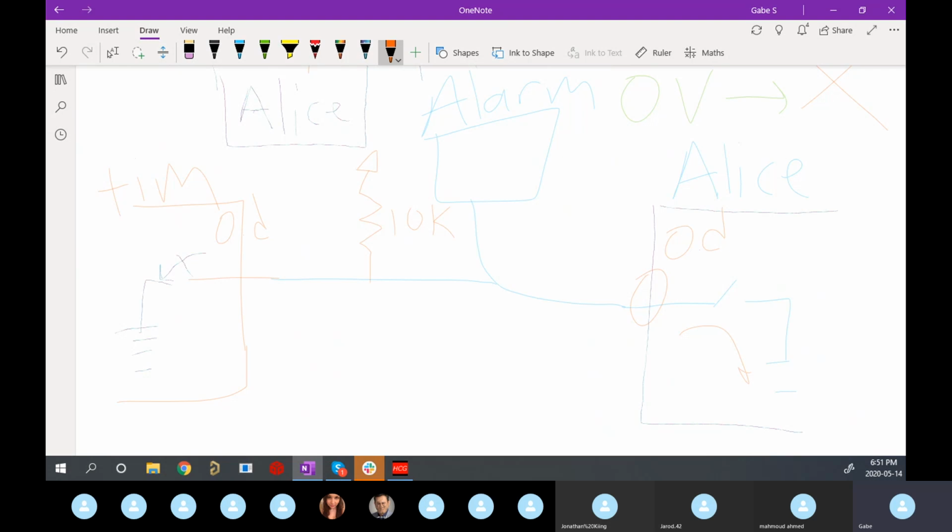We're not going to have the situation where Tim forces this to 3v3 and Alice is forcing it down to 0 volts. Neither of them have the capability to do this anymore. So if any of them see a fault, they can both, or just one if only one sees a fault, close their switches. For example, this is done in code, of course. This switch is just an illustration, but your GPIO would output a 0 volts at that signal. They can both switch it to ground if they want, or only one of them can switch and the other can let it float.